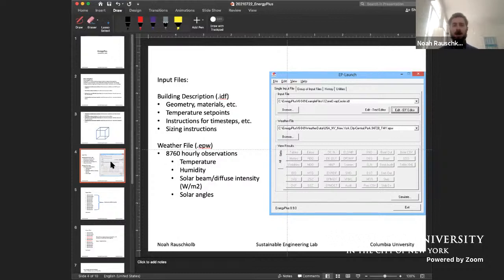There are instructions for how to run the model, and depending on the physics of the building, you may say, well, an hourly time resolution is adequate, or if you've got a building with much faster transients, you might want to go to something like a 5-minute time step. And I'm sure people will take that even further and try to do sub-minute time steps. I think EnergyPlus is flexible enough that if you were really determined to go to a very high resolution, you could.